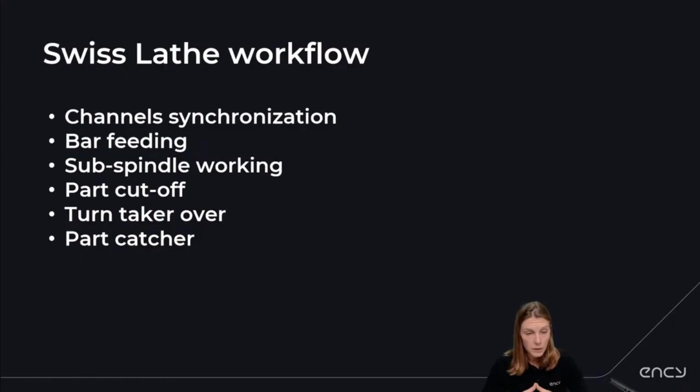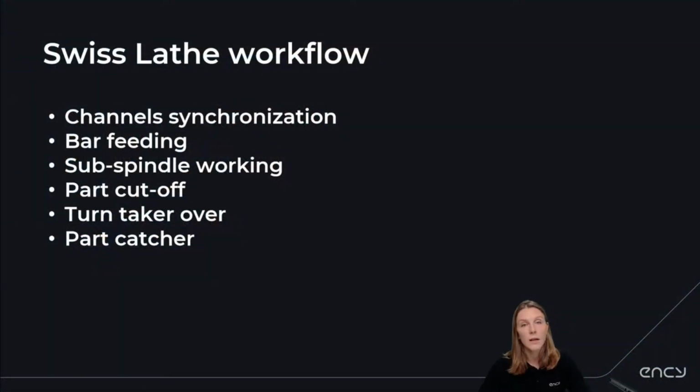Having this setup already done, we need to program, again, besides cutting operations, multi-channel synchronizations. We need to program bar feeding, because Swiss lathe programming is almost impossible without bar feeding. We need to take care of the subspindle, of turn takeover operations, and we also need to program cutoff and part catchers. So you can see that that's one of the challenges that I mentioned at the beginning, which is not so easy to manage for the Swiss lathe programmer.